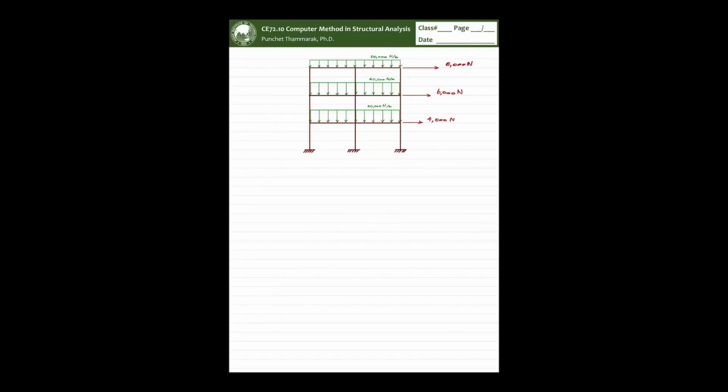And if you cannot come across the issue in the simple model, never proceed to the complex model. Alright? Always come back. No matter, when you go to the design office, it depends on what platform they purchase. SAP, STAAD.Pro, whatever, Robot, you cannot choose. And when you come to the new platform, you might not understand the nature of that platform that well, right? So please check a little bit. If I were you, I would always check simple cases and make sure.